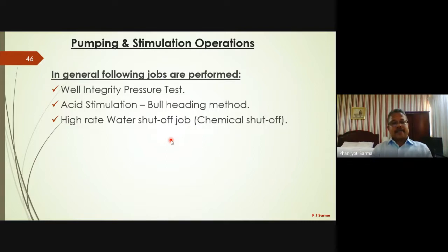Then high rate water shut-off job. Sometimes in order to carry out the chemical shut-off jobs or sand consolidation, we can do the high rate water shut-off job with the help of this pumping unit or the stimulation unit. A high volume scale squeeze job,